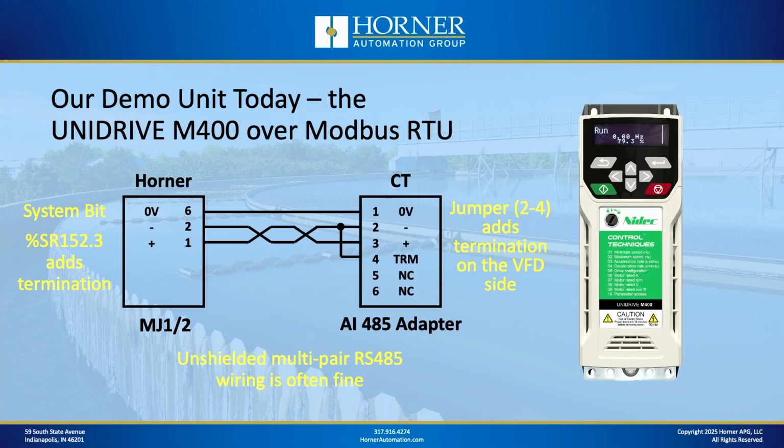So you'll need one twisted pair to handle the actual communication signals, and then at least half of another twisted pair or an extra conductor that's used as a common. Now, why do you need that extra conductor as a common? Well, that's because of something called common mode. RS-485 supports some distances that are large, and you can have scenarios where the voltage reference for the communications is beyond the common mode limits of the equipment. So by having that common conductor, you eliminate that problem altogether.